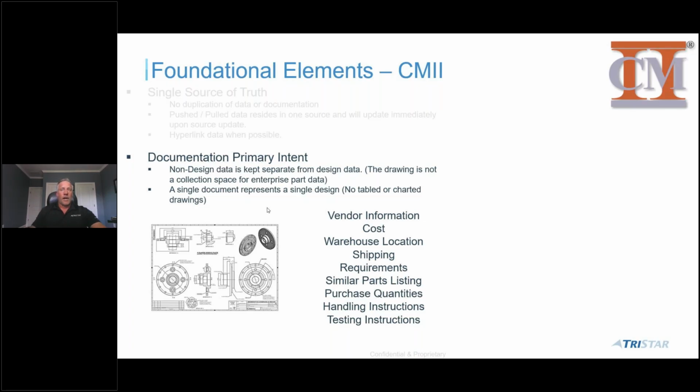And most of these things we're going to tell you need to be documents. Now items that have additional capability in Windchill, like handling your suppliers, right, and AML, AVL, that kind of information, actually can be done in a different way in Windchill. There's core capabilities in supplier management that allow you to do that. So we would still advocate that there are items that may be on your drawings today that actually should not be attributes on your WT part. So for example, things like supplier names, right? Supplier part numbers, those should not be on your drawing. They should not be attributes on your WT part.